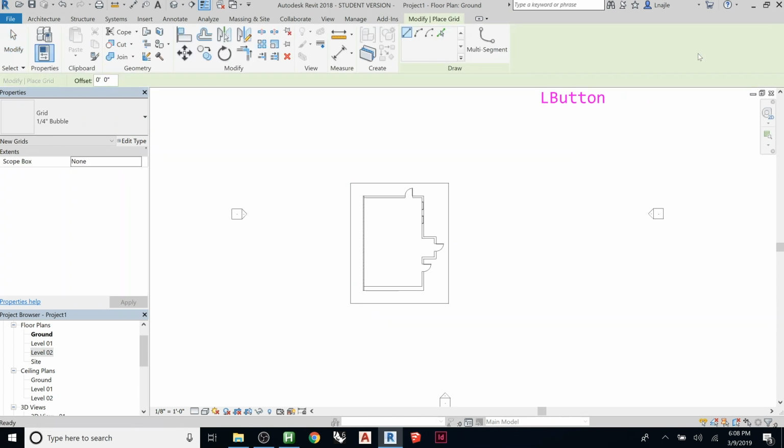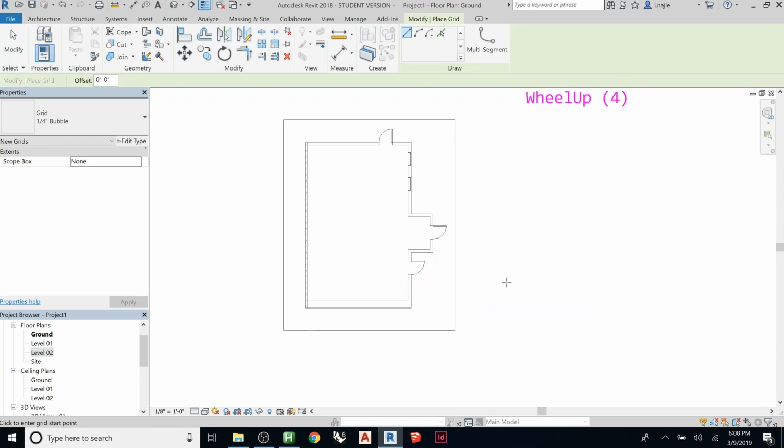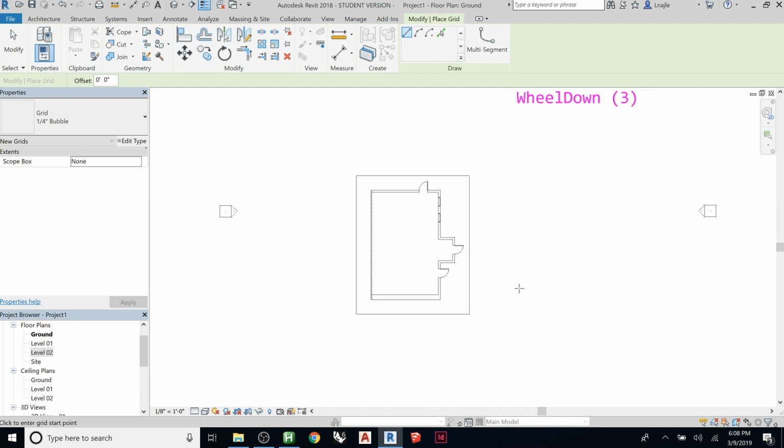So in the floor plan, I can create this grid, and just like we did before, we can start off by going from here. So it's nice because it's going to kind of snap. So I'm going to click there and draw my line over. One, let's say like that, could be two, and let's say here, could put grid line 3. Now, if I want to go in this direction, we can do that too. I can click here, and it's going to name that number 4.